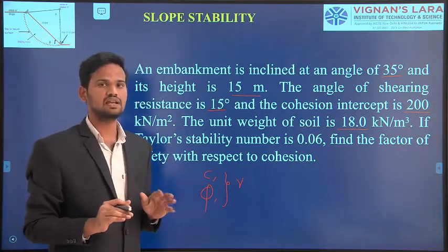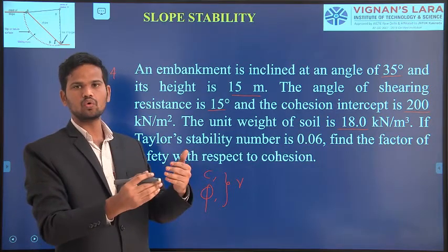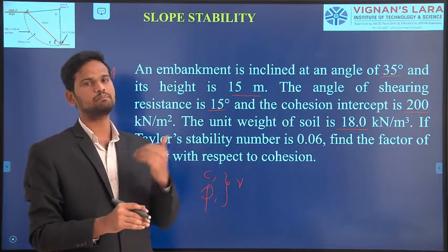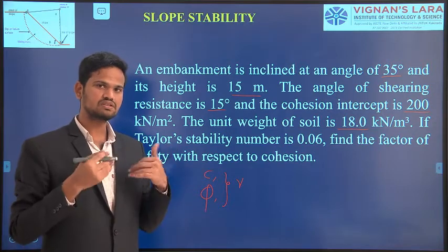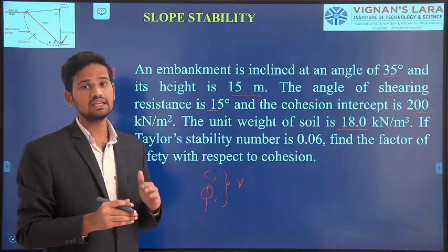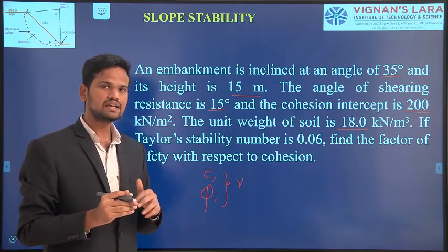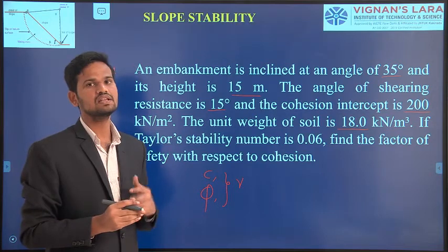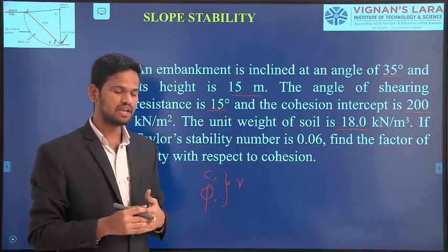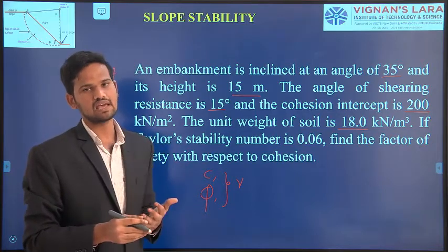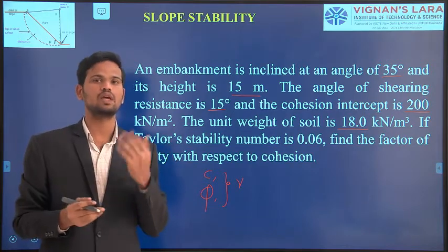See, basically the soil is first in the loosest state. If you compact the soil, due to this compactness, the air voids may reduce. Due to this reduction of air voids, the density or unit weight of the soil mass may increase. Due to the increase in unit weight, the effective stress may increase as well as permeability may decrease. Due to increasing effective stress, the bearing capacity value may increase. That means you can apply a maximum amount of load.